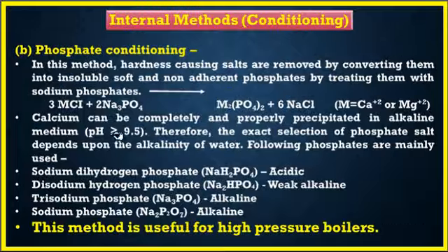Next is the phosphate conditioning. The basic fact of the phosphate conditioning is that sodium phosphate is added to the boiler feed water which contains calcium or magnesium salts.